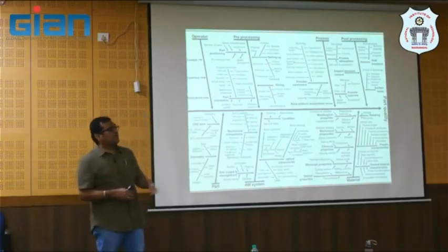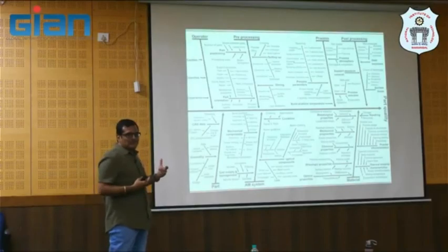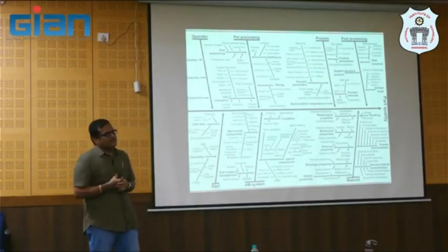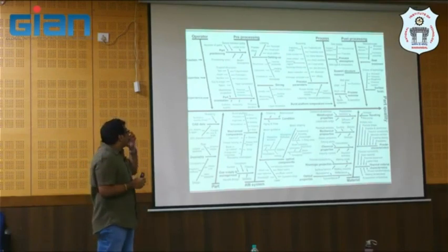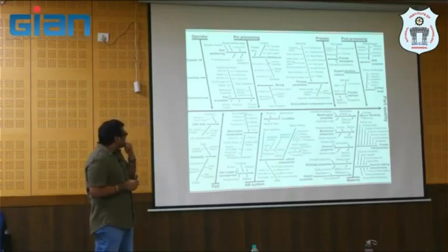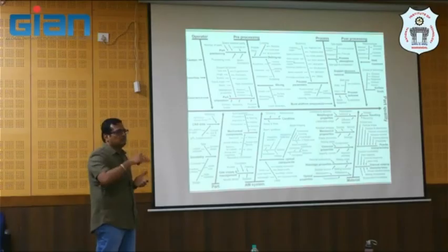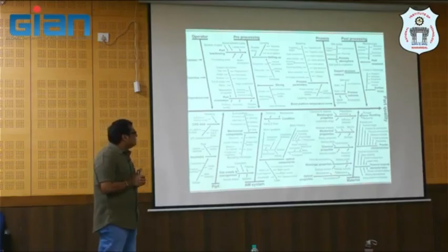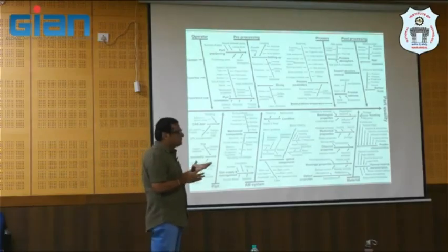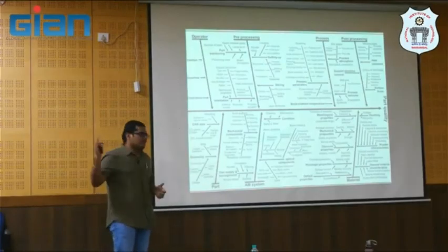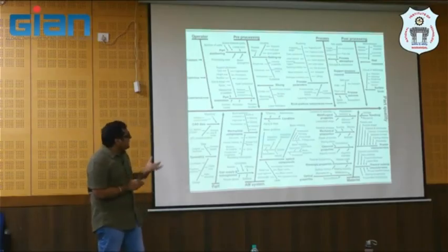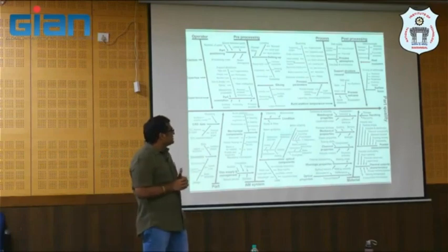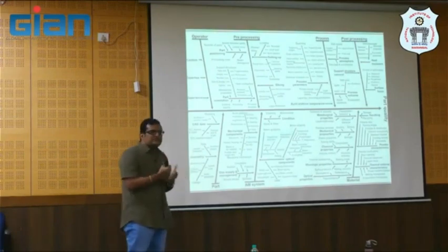But you cannot do everything by design, during the process, or during feedstock preparation, or during the interaction of energy with the feedstock. And you have operator pre-processing, during slicing, part positioning, part orientation, and setting up process parameters, from layer thickness to laser power or energy density. So you have those process-related parameters, and of course post-processing at the end: support structure removal, heat treatment, surface treatment.